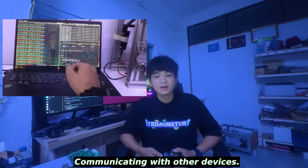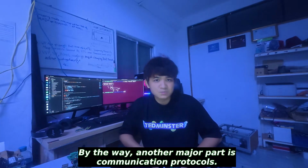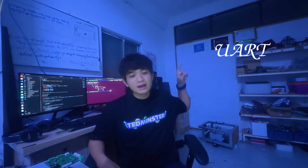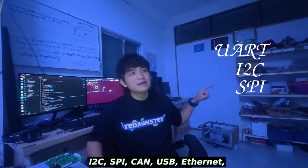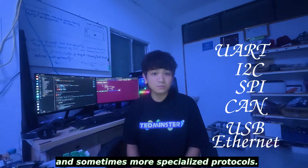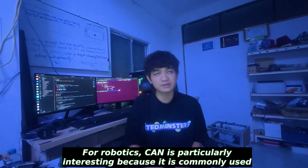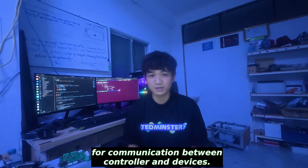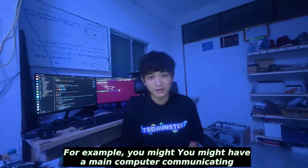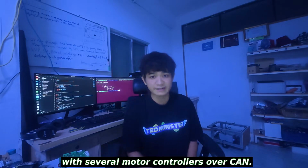By the way, another major part is communication protocols. You will often encounter things like UART, I2C, SPI, CAN, USB, Ethernet, and sometimes more specialized protocols. For robotics, CAN is particularly interesting because it is commonly used for communication between controllers and devices. For example, you might have a main computer communicating with several motor controllers over CAN.